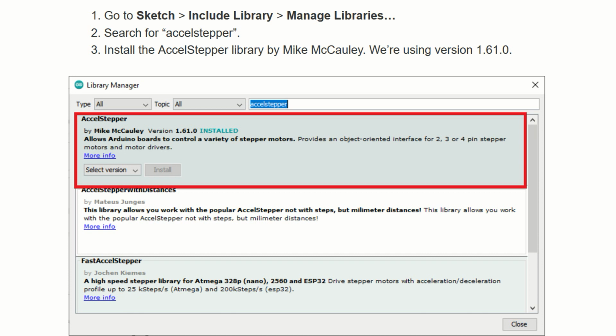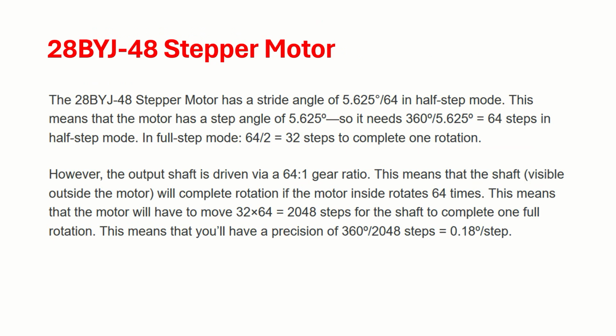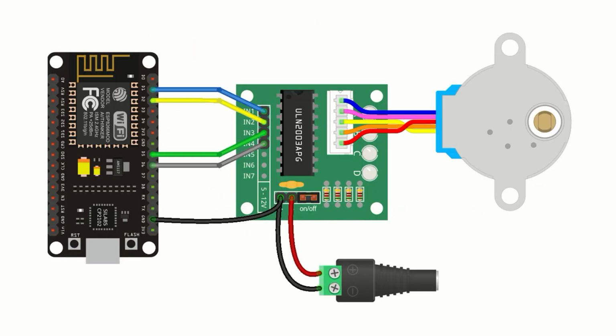Because finally, I was telling about the combination. If you want to give the half step, full step, and the forward direction, reverse direction, the pulse is not one. Here, the pulses are at least a four pulse pattern to make one step. So that is the combination.